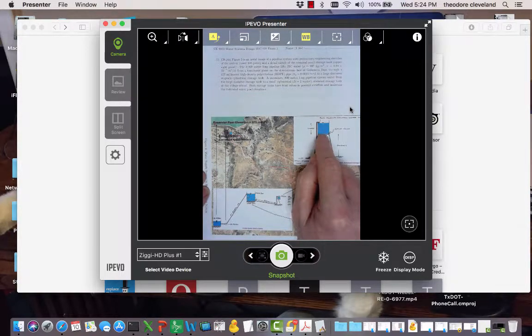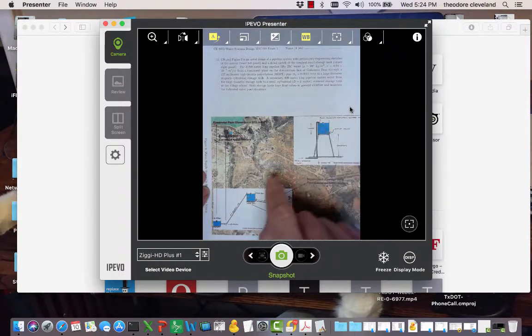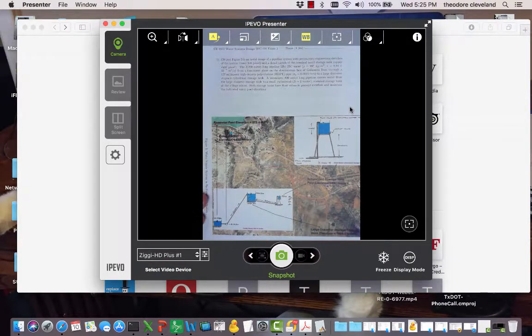This small tank has a diameter of 1 meter. It's 3 meters, the bottom of the tank is 2 meters off the ground, 3 meters to the top of the pool. The tank has a float valve, as does this one, to maintain the water depth and to stop flow once the water is deep enough. It says both storage tanks have float valves to prevent overflow and maintain the indicated pool elevation.